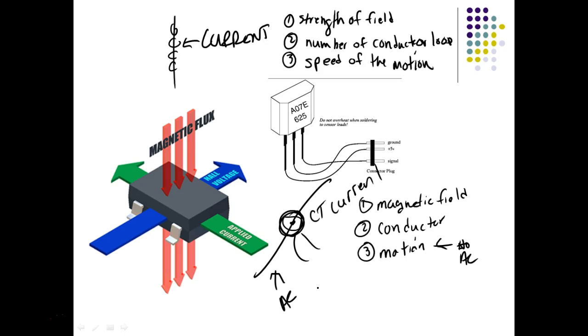Well, how does it measure DC? It uses a linear Hall effect. And these cost a pretty good deal of money, DC and AC clamp-on ammeters. But the problem is they're rated at extremely high current. So if you ever look at a clamp-on ammeter, usually the lowest current it'll measure reliably is like 40 amps, and then it might go up to 400 amps.